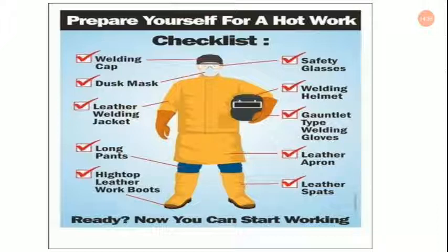Now, explosion hazards. Because of the explosive nature of welding gas cylinders, you have to pay particularly close attention to their storage and use. You have to examine the cylinder and check the label to ensure it is the correct shielding gas for the process. You have to check that regulators, hoses, and fittings are the right ones for that gas and pressure and are in good condition. Cylinders must be stored in an upright position with the valve caps in place in an area away from combustibles and fuels and safeguarded from damage, heat, and flames.